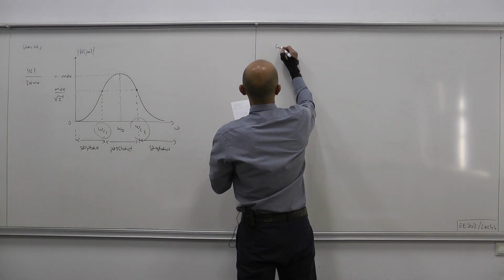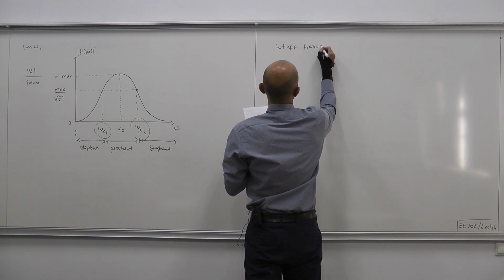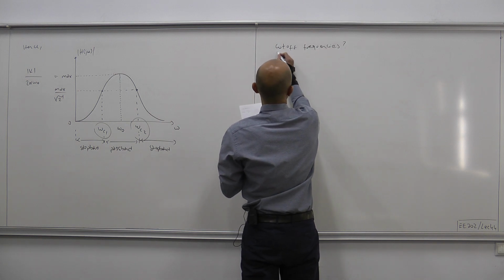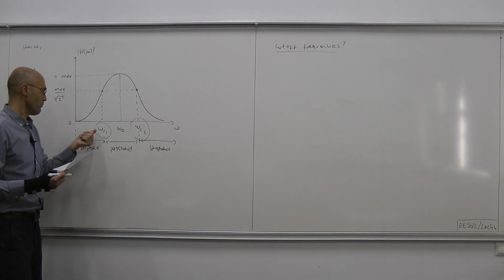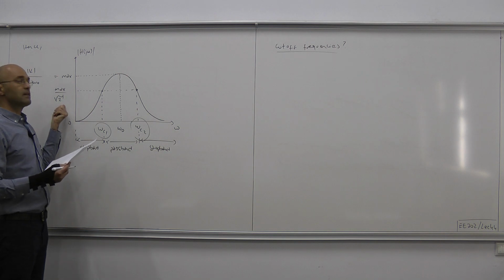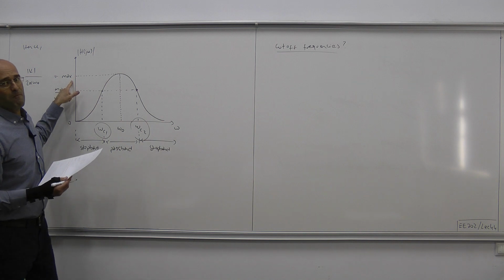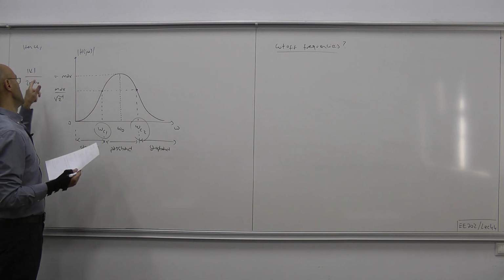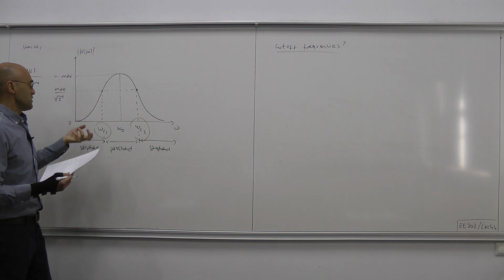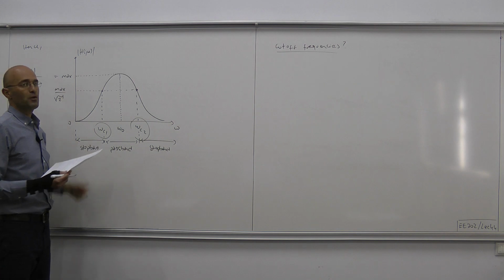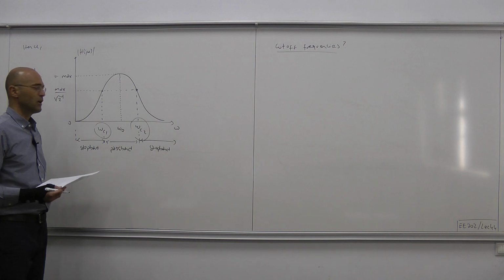Let's figure out omega C1 and omega C2. The definition of those frequencies is clear on the figure. You figure out the maximum value that the gain can achieve, which we did, and then divide that by square root of 2, and the frequencies at which the gain achieves that max over square root of 2 value are what we're calling the cutoff frequencies.